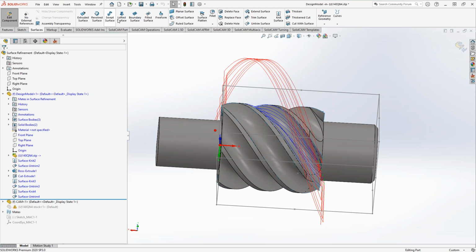And then once you get the surface-based functionality, you can do a lot of good geometry for your 5-axis, for your 3-axis work. There are some times where I would add a surface for gouge checking. A surface that isn't even part of the part, but if I make a surface that happens to represent just a wall that I don't want it to pass, rather than doing any of those limit by number of cuts or limit by 2 points in HSS, if I draw an additional surface and just say that's my check surface, then I can trim the toolpath a little easier than if I tried to manipulate link between slices, limit by number of points, any of those kinds of changes or modifications.